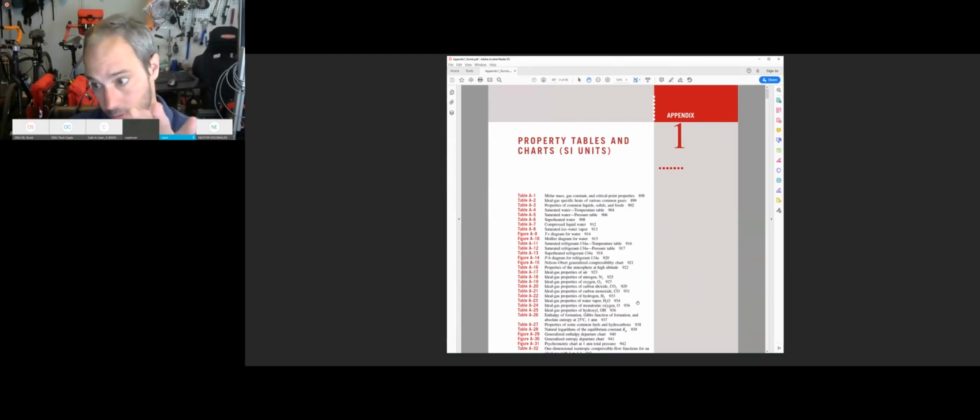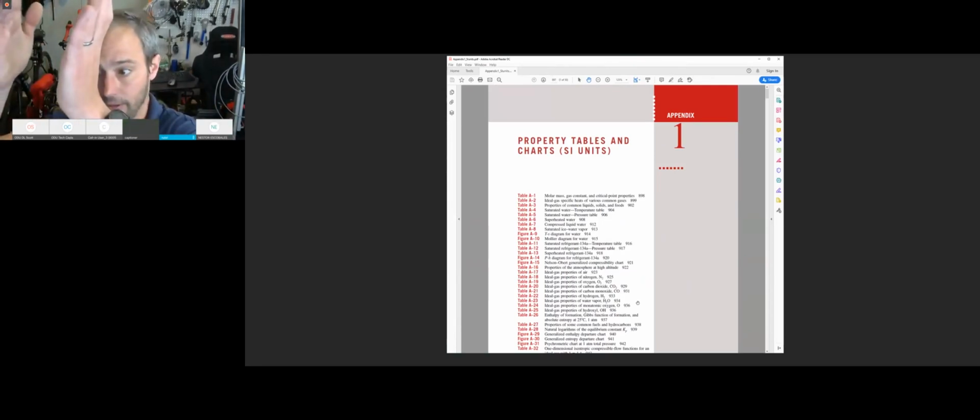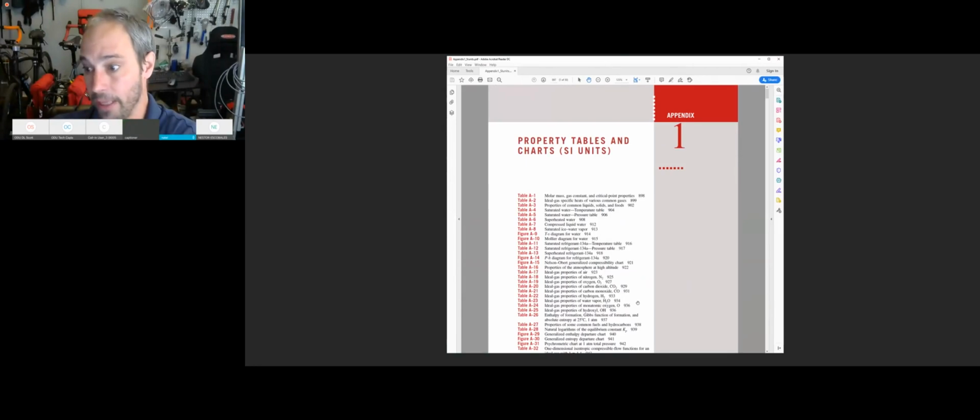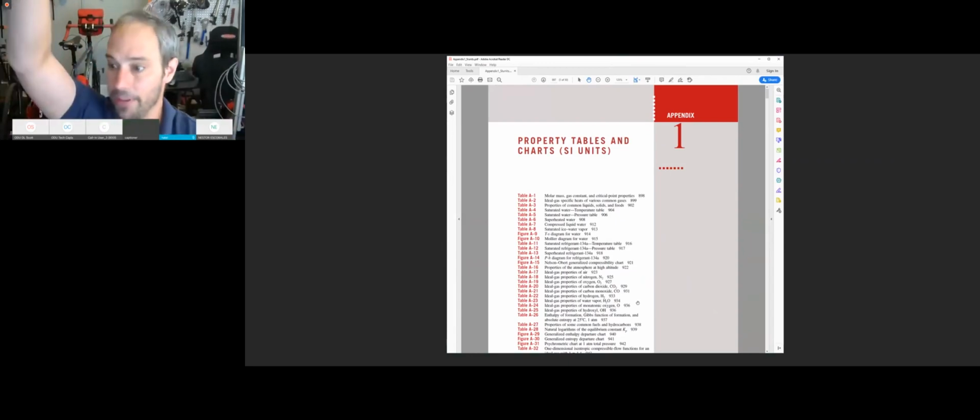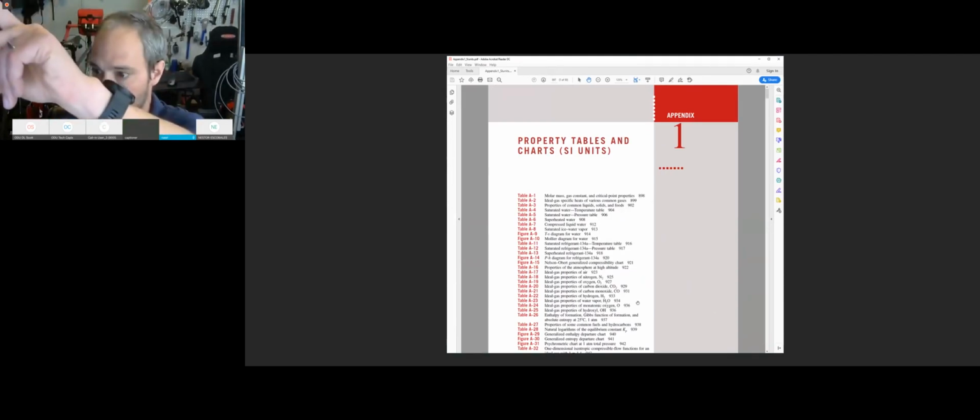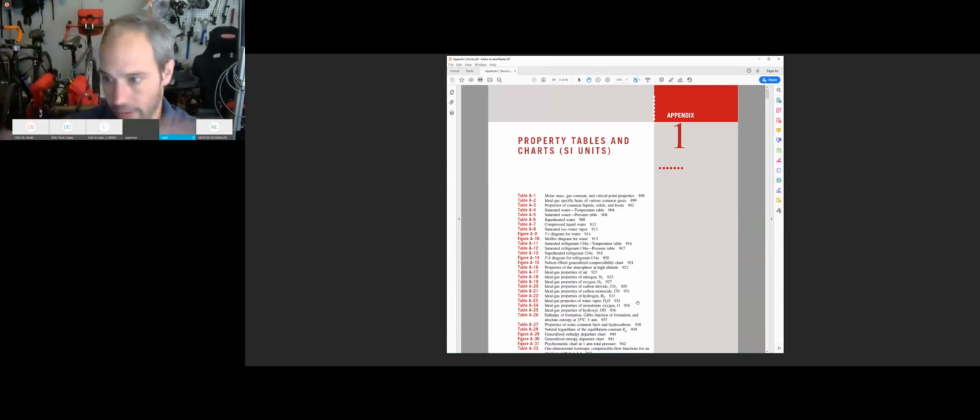of the water, and whether it's just beginning to boil, we call that a saturated liquid, whether it's during the boiling process, we call that a saturated mixture, or whether it is on the just completed boiling, it's all vapor, saturated vapor. Then you've got superheated region, which is what we call where it's beyond boiling, and you got compressed liquid, which just means it's not about to boil. We don't care about that. Very tippy top is called the critical point, and that's the end of the line on the property diagram. That's all chemistry right there.